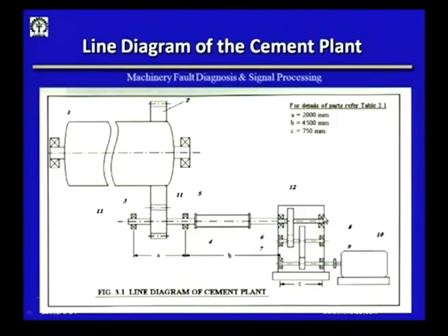Suppose I put a transducer here, it will be capturing phenomena of all the gears, capturing phenomena of some of the gears here and bearings. So, now the question is which bearing has a fault, and that is what, if you do the analysis, you will see that the same problem occurs: which sideband corresponds to where and how do I find that.